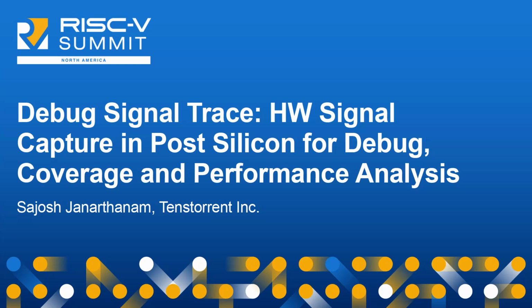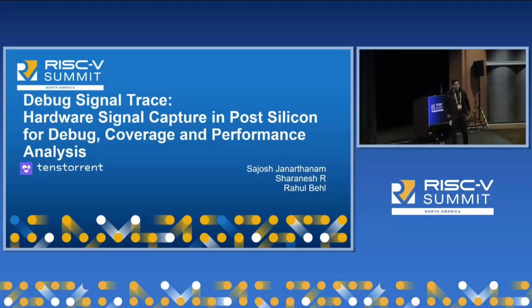Yeah, so the topic we are going to cover today is, as he said, debug signal trace. This is a hardware mechanism to track and capture microarchitectural events in post-silicon, not only for the purpose of debug, but also for coverage and performance analysis.